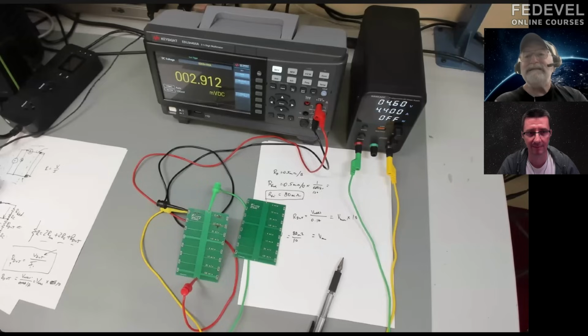And so at DC, the current's going to take the parallel paths, and you have to figure out how much current's going to flow and where the voltage regulator modules are going to be. That's where you need 2-ounce or 4-ounce copper for the planes, multiple power planes, and multiple ground planes as well.